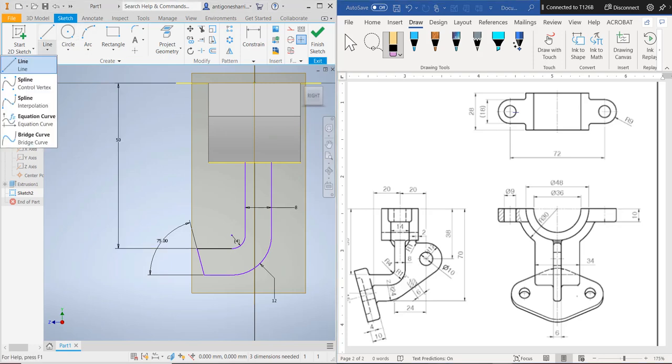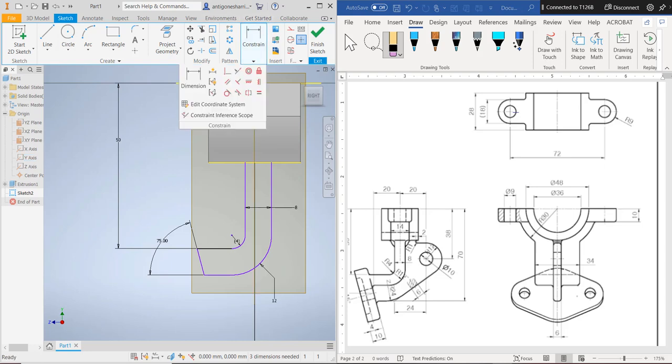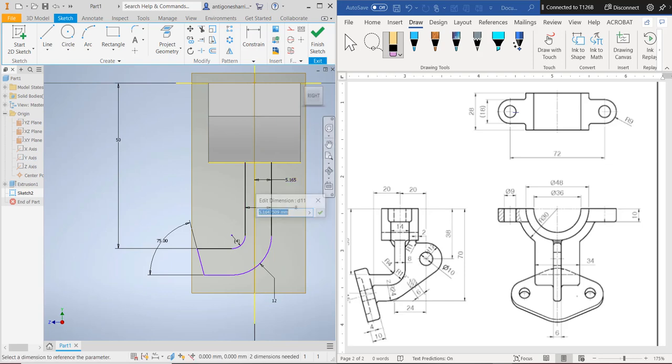So the way that I can build this in to try to get this dead on is I have my center plane. So I'm going to pick this object, pick here. Okay, whoops, first I got to go into constraint and dimension, sorry. Pick the center of this, pick my side wall, go out here, and I'm going to pick this object, f of x, not minus, divided by 2. That's how I position it correctly.